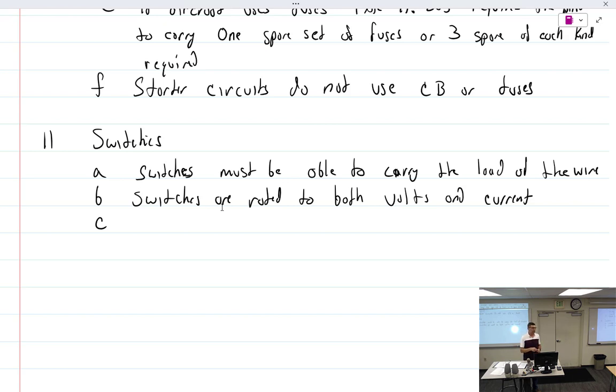Anyway, I was just scrolling through it and it had videos, Cessna videos. I'm like, video? What are they possibly? And one of them was kind of cool, 15, 20 seconds. But it actually showed why they put diodes on solenoids, like the master solenoid. I'll work that into the lecture at one point. What they did is they took a master switch. When you get in an aircraft, everything's off, it's dead. You hit the master switch, which opens a relay, as I said solenoid, but a relay, which brings power into the bus and the aircraft is on.